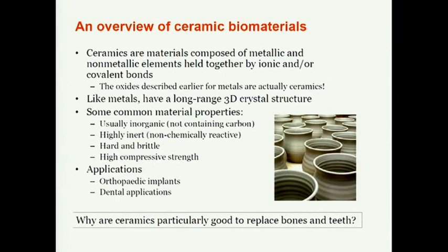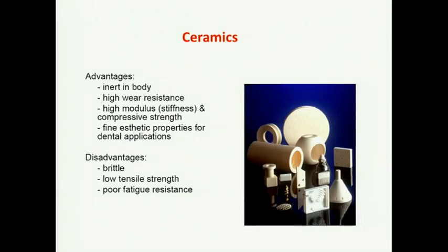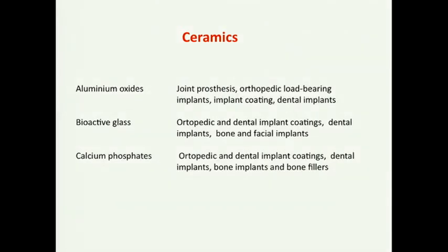They are highly used because they can carry a high amount of load. The advantages are that they are inert, with high wear resistance, high modulus, and high stiffness, so they are important in load-bearing applications. The disadvantages are that they are brittle, with low tensile strength and low fatigue resistance.